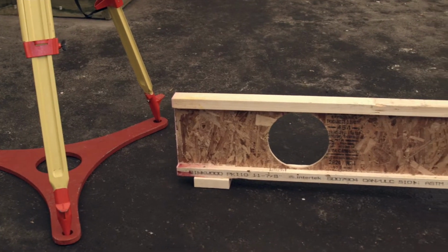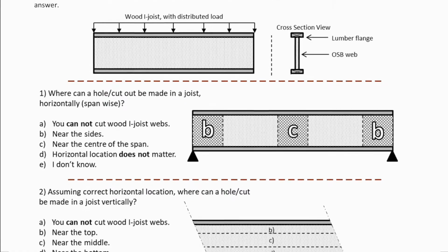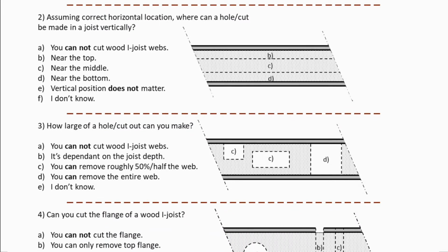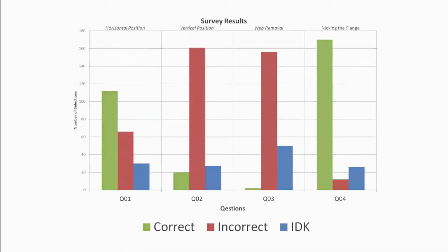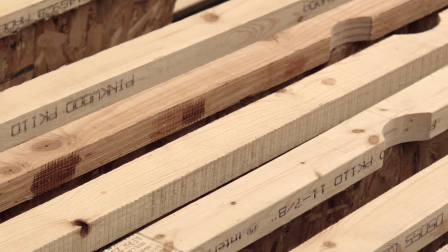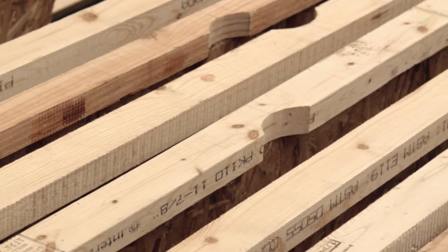We investigated how much the incorrect cutout placement was an issue by looking at graduates' opinions, contacting the industry, and chatting with city inspectors. 201 students were surveyed from civil engineering techs, plumbers, and HVAC. Not one single person surveyed attained 100%. These are going to be the new hires that will be going into the field and making a first-time mistake. The residential construction industry was reached out to, and it was found that the biggest issue they have is the top flange being nicked. As such, we wanted to show the dramatic effect of what happens to a nicked flange.